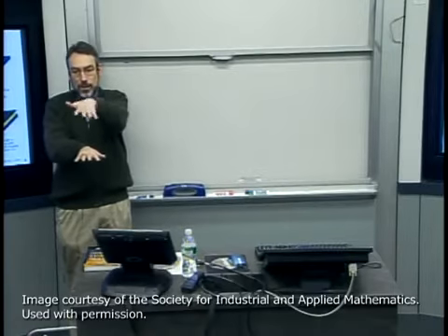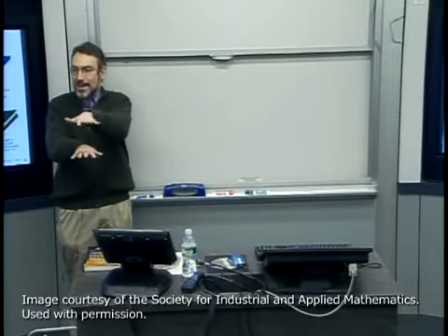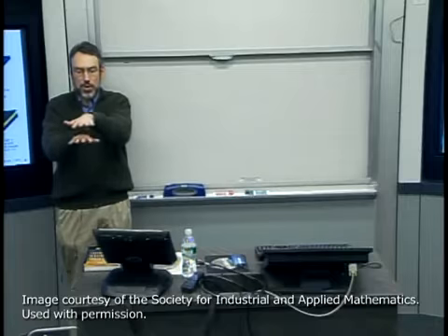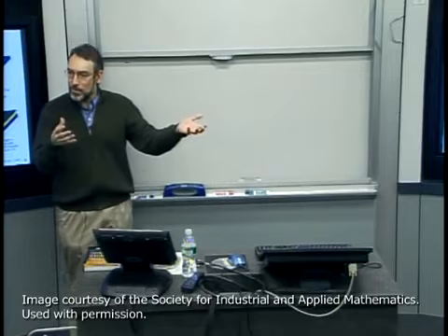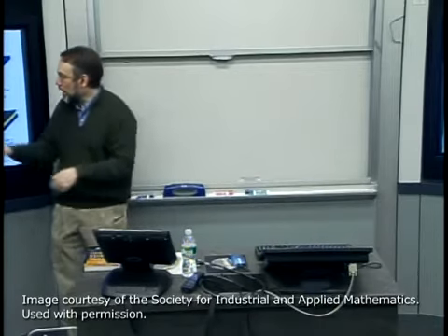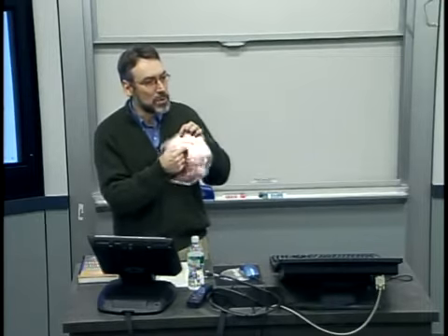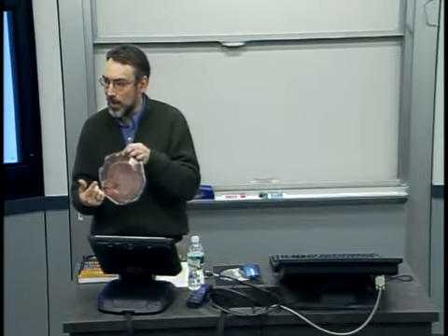It's a huge challenge to then line that up with the physical mask plate such that you minimize offsets. There's also exquisite environmental control in the equipment that's used for this. Imagine that I don't need to line up just for one transistor. I've got to make sure across maybe a 1 centimeter squared or 2 centimeter squared chip that all of my transistors are lining up.